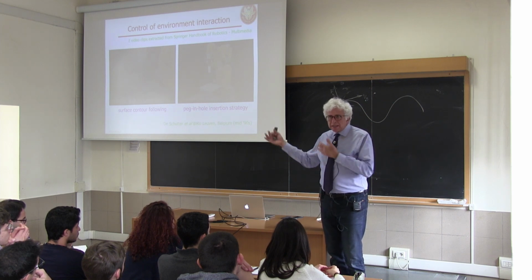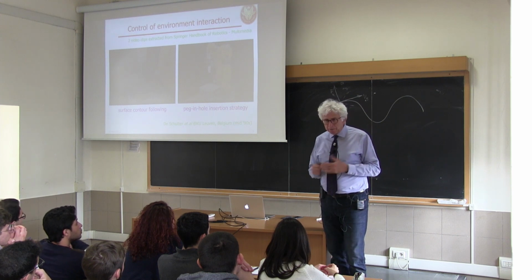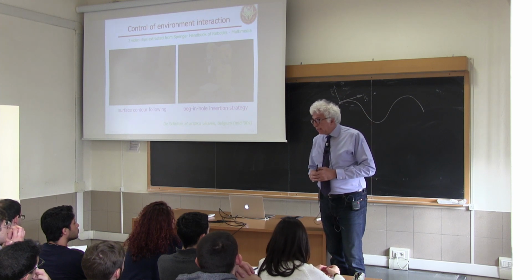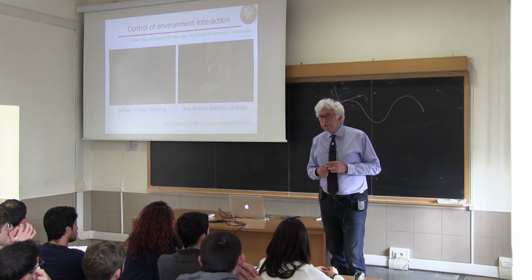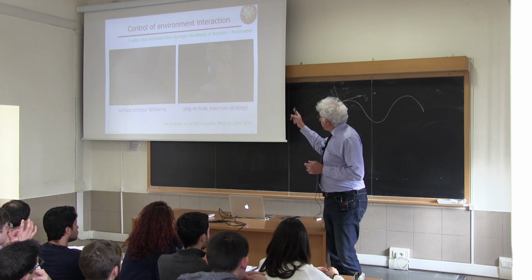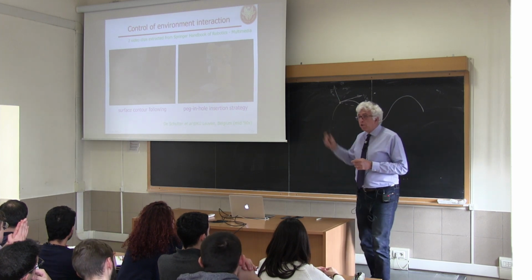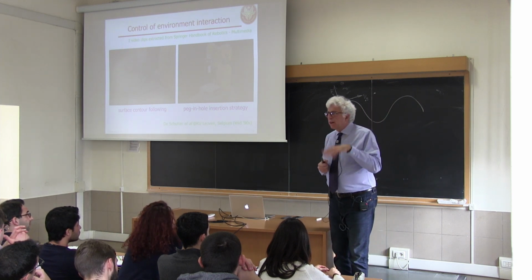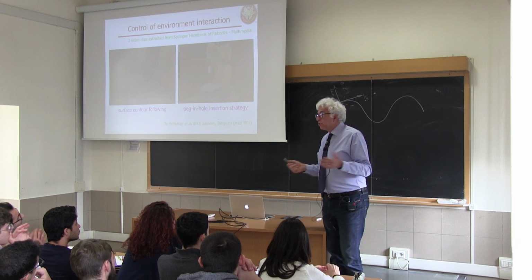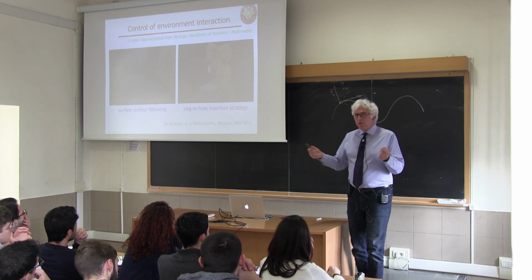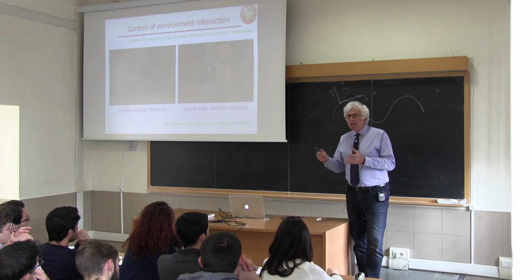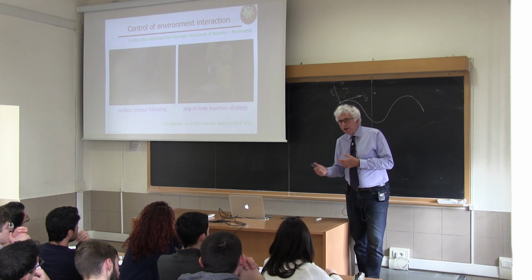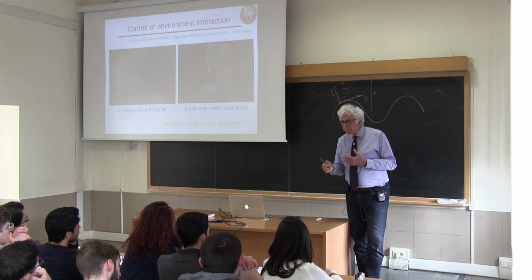So it means that such assembly can be done also with pure position control, provided that you include some compliance in the structure. And the typical way is using such an RCC device. Even the gripper of the Leuven setup has some compliance. If you notice, the peg was vibrating a little bit. Of course, once you introduce this passive compliance, so a form of springs that are not controlled, you may induce some vibration. And so you reduce the accuracy, especially if you're going fast. So there are pros and cons in this.